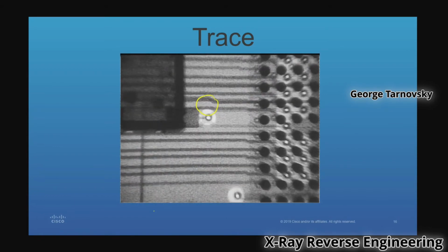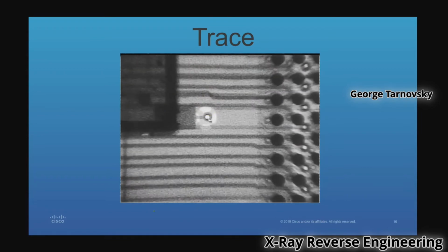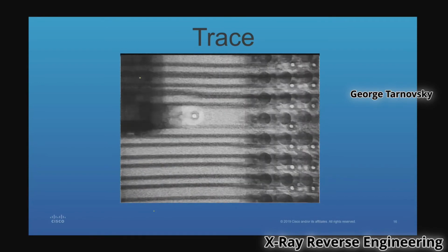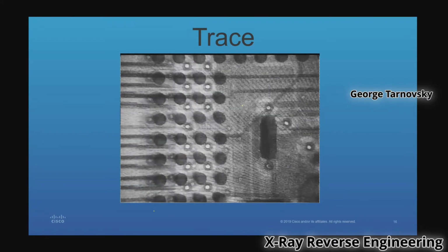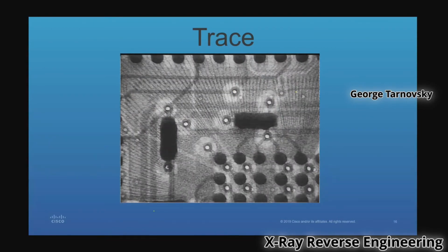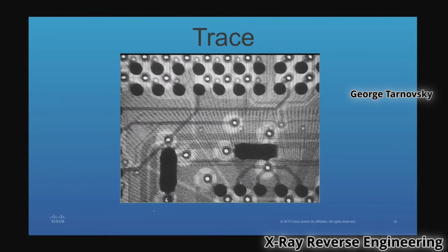And you can see it got grainy because I had to change the sampling rate. So now it's pretty evident that this goes like this, right? So now we'll continue. And so you can see the bond wires in the BGA. You can see the edge of the die right here and the bond wires. So you're seeing through all of that. We're still tracing. But anyway, this is our final point. That's where we were going. So that would be typical and what we do using the X-ray.